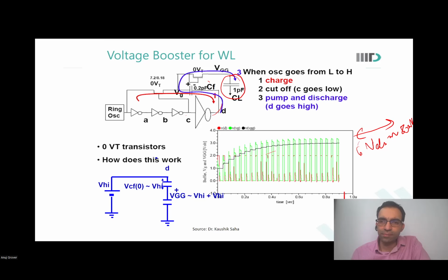Sir, regarding the refresh, I have a question. In the read operation, refresh is anyhow going to happen. So the other refresh we were talking about, which will happen at 3 milliseconds, is independent of the read operation, and 3 milliseconds after the last operation, refresh should happen. So it is 3 milliseconds after the last refresh or whatever. Yes. So is there any counter? Who will manage the 3 milliseconds? Yes, the counter will be inside the controller itself. Okay.